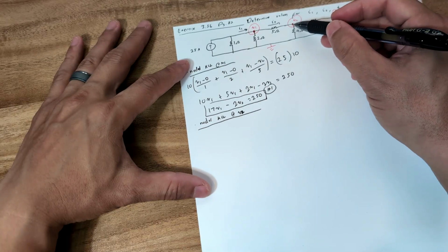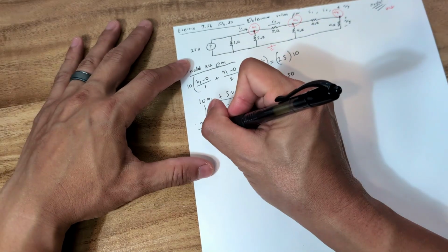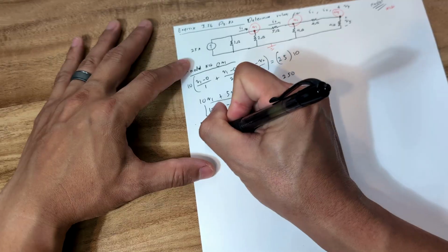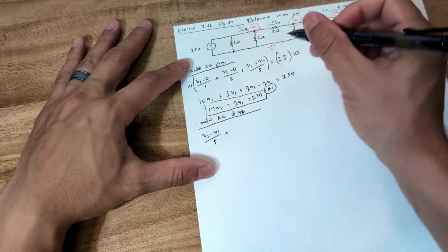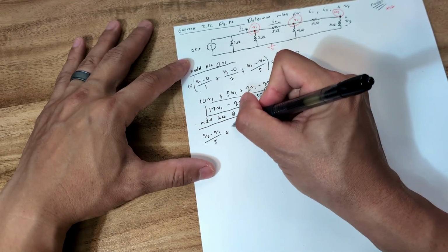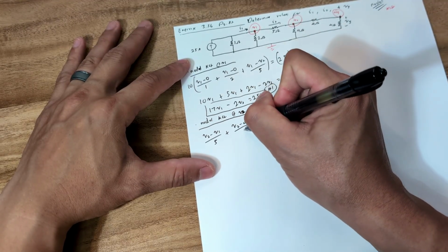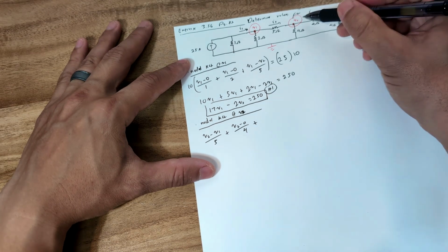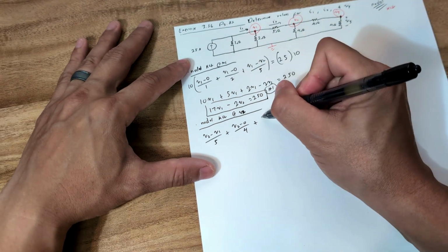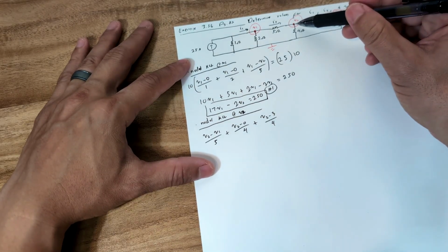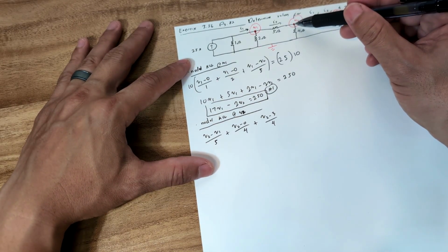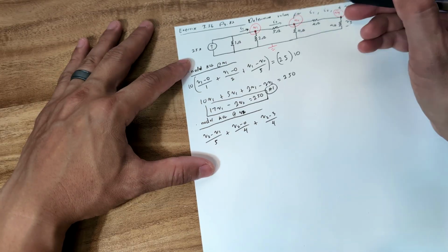So it's going to be V2 minus V1 divided by 5 ohms plus V2 minus 0, because that's ground, over 4 ohms plus V2 minus V3 over 4 ohms, and in this case there's not any dependent or independent currents coming in,